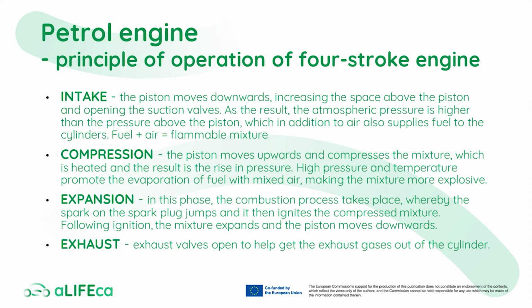Third stroke is expansion or power stroke. In this stroke, a spark plug ignites the air-fuel mixture, and the resulting combustion quickly expands the gases, forcing the piston back down the cylinder. Fourth stroke is exhaust. In this stroke, exhaust valves open to help get the exhaust gases out of the cylinder.